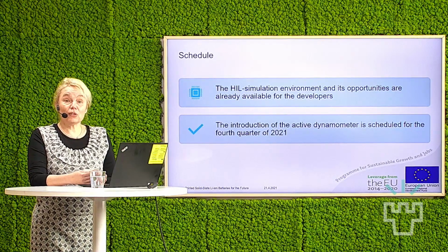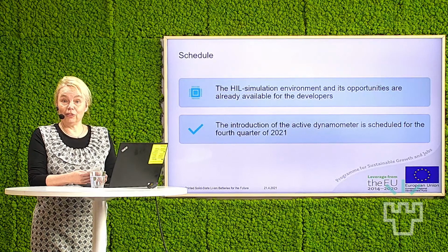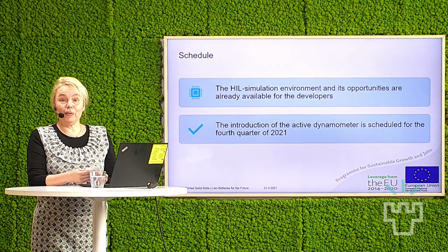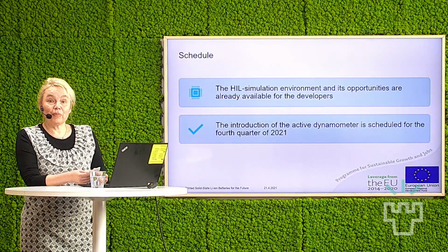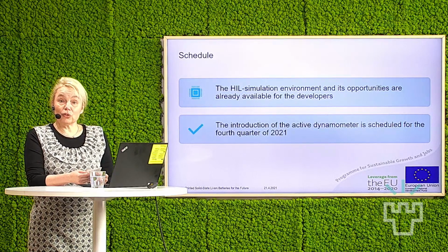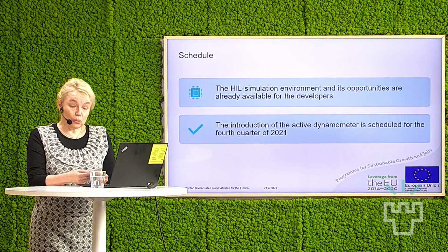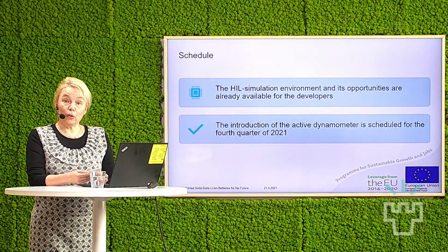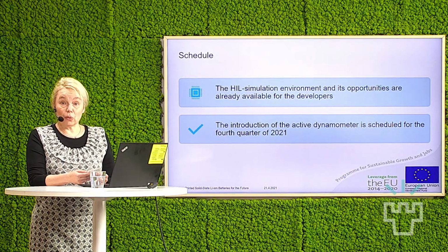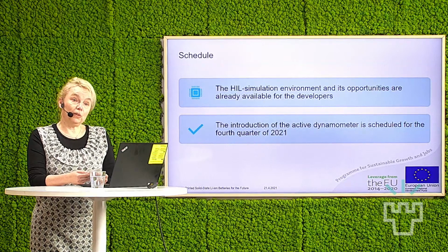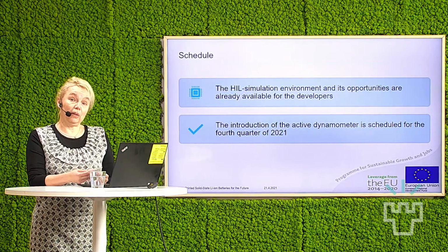The first question was related to the ionic conductivity of those solid electrolytes, and as I already mentioned in the first presentation, the ionic conductivity of the solid electrolyte is a key issue. Of course, when we go from liquid phase towards a solid phase, the diffusion of the ions will be slower. And there might also be some mass and heat transfer limitation inside the battery cell.